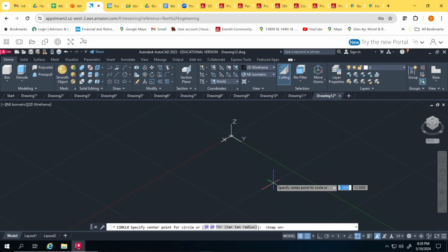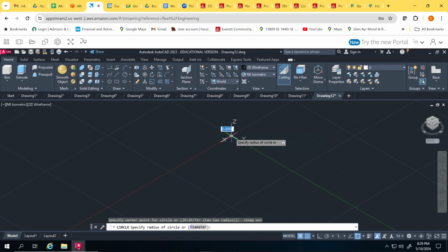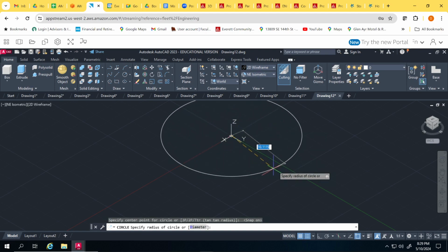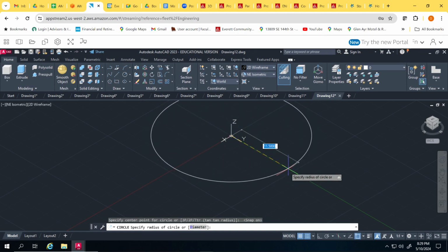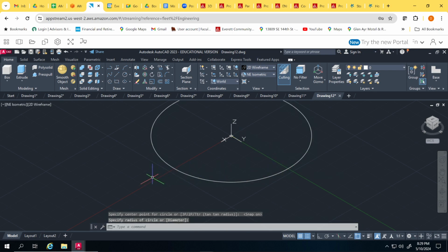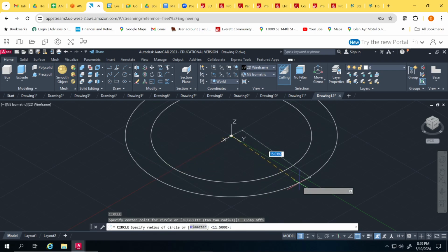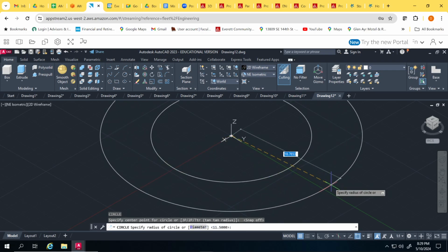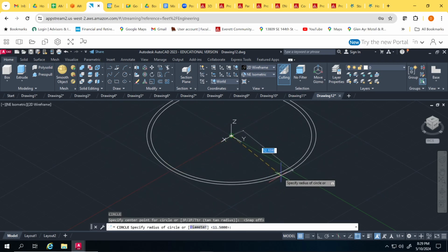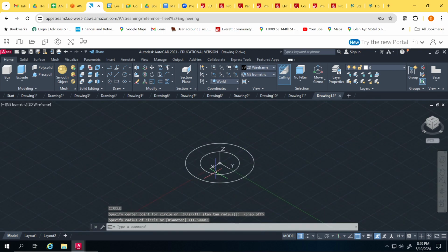active, I'm going to come here. And I'll just come out. We'll make this simple for me to see. I'll come out to here. And then I'm going to hit enter. And then I want to get on the edge of that circle so I can find that center. If I have a hard time getting the edge of the circle, I'll turn the grid off, the snap to grid off, and then go to the edge. Now it's the center. So now I know I'm making a circle concentric to the other circle. Just click a location, I'll zoom down.